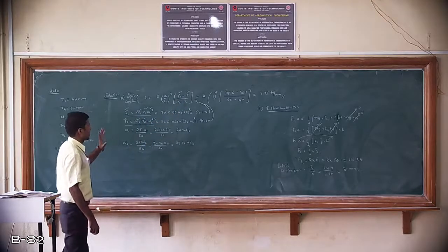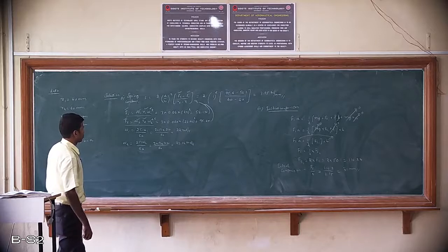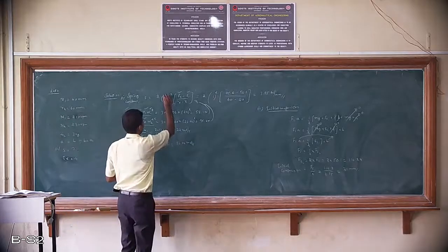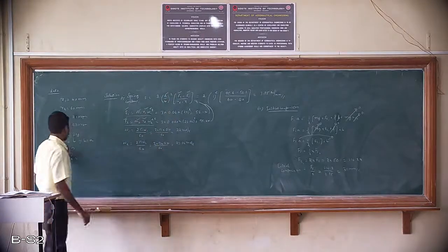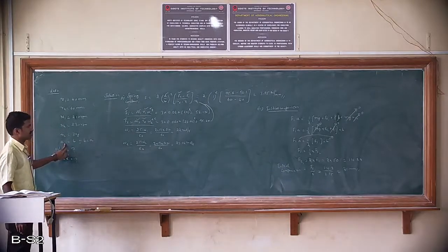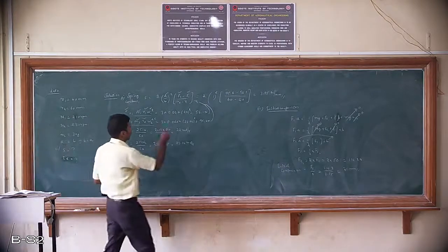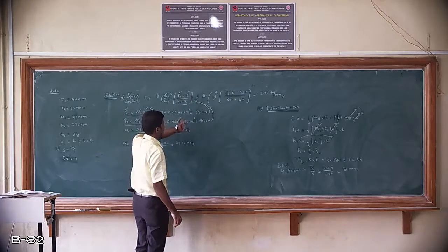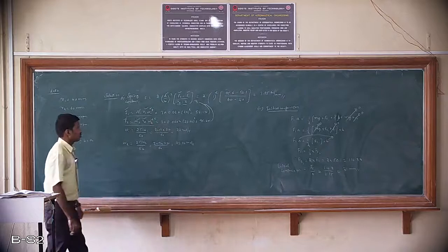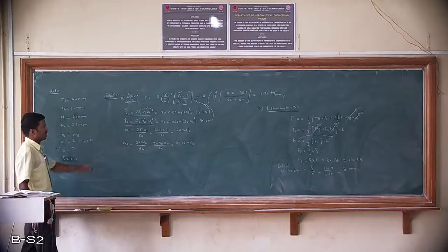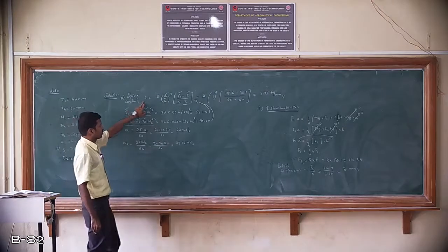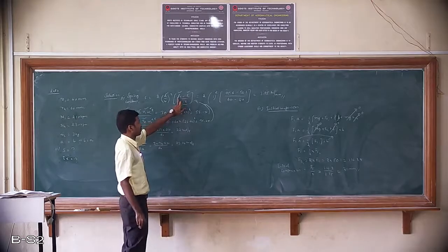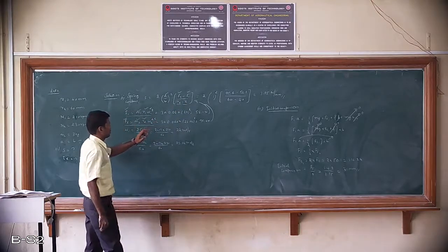If I analyze this governing equation for the spring constant, the A and B values are known, as they are equal. He has clearly mentioned the lengths of the ball and sleeve arms are equal. R2 and R1 values are known, but the only unknowns in the equation are F1 and F2. So it means that to get the value of the spring constant, we need to find the values of F1 and F2. So how do we find F1 and F2?